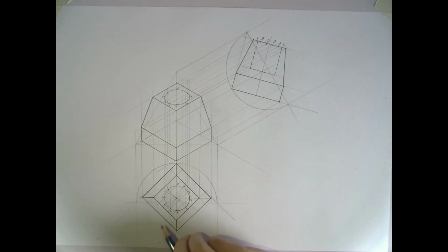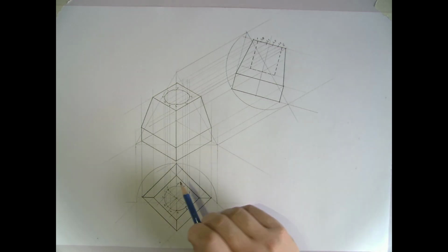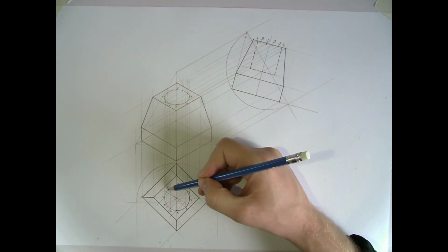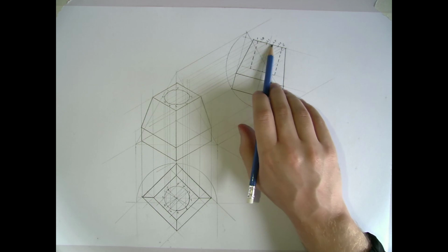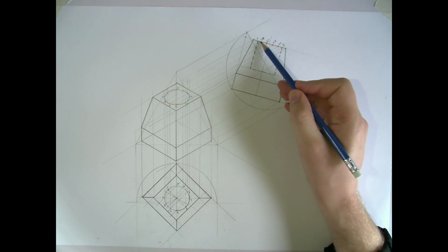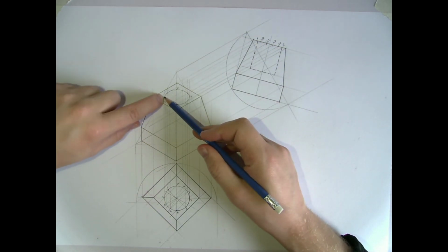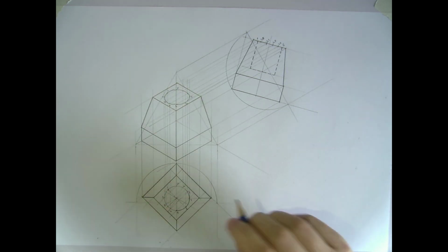So just a quick recap on what happened here. Divided this circle up into a number of equal parts, or they don't have to be equal, it just makes it easier if they are. Took the distances, the left-right distance, so 1 to point 2, 1 to point 3, 1 to point 4, and so on, and marked those same distances up here in the elevation. Then point 2, for example, was projected down along this way. Point 2 from the plan was brought up to meet, and they intersect at this point, giving me the point on the curve, same as where the other points were drawn. So that completes